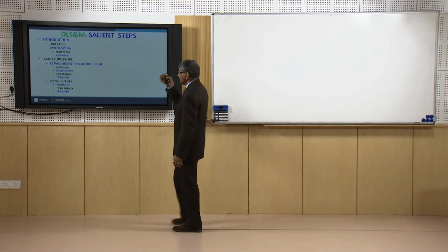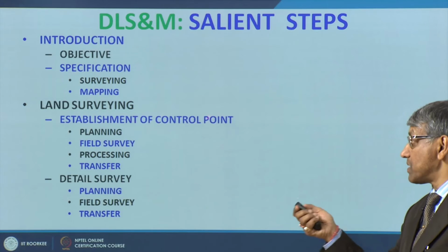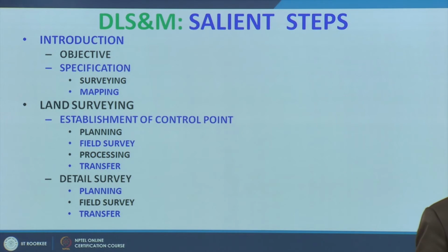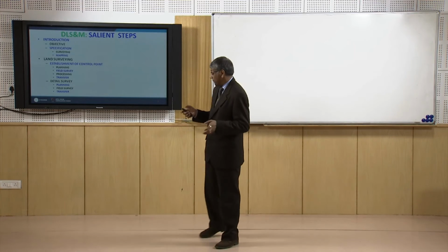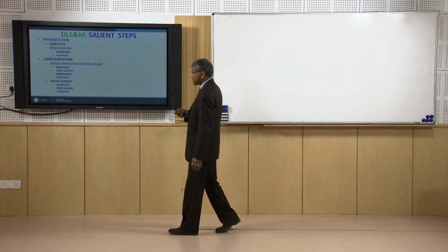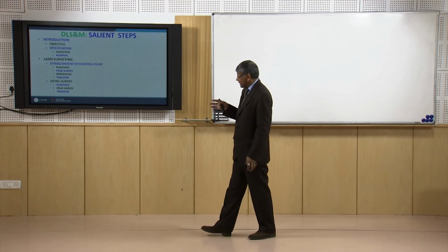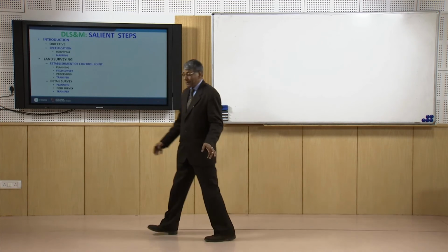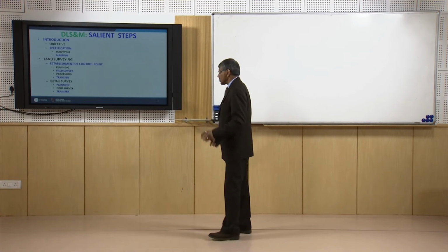So from the GPS survey, establishing control points, at least 2 control points we will like to provide for carrying out our field survey work using the total station, and those 2 points will be used by the method of backsighting to